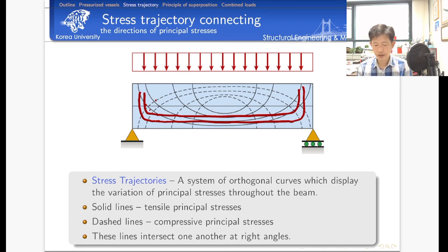And then what is another layout that we can consider in practice? We put the reinforcement, and then we kink the arrangement of reinforcement like this, typically following 45 degrees. That is following the development of the stress trajectory near the support.